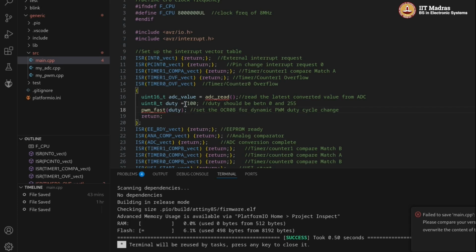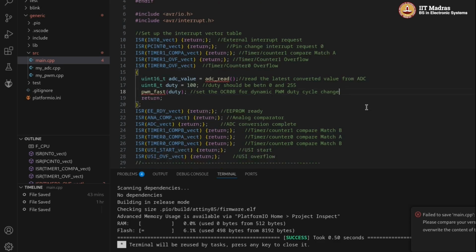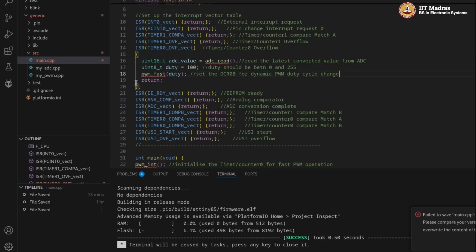So now you see that everything is compacted in the form of functions and they are placed in the modular mypwm.cpp and myadc.cpp. Next, when I discuss the PI controller, you could have one more module, mycontrol.cpp, with a control algorithm in between ADC and PWM.